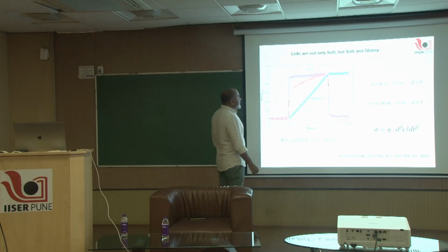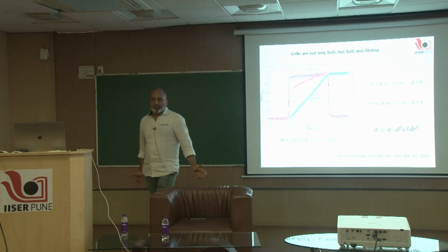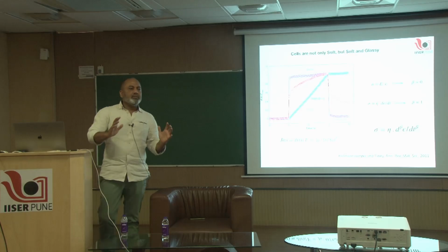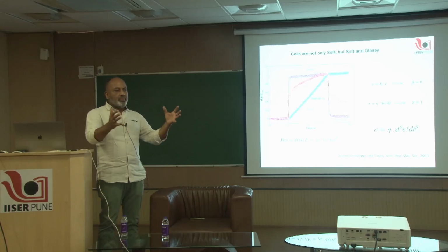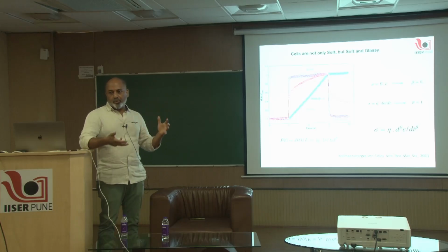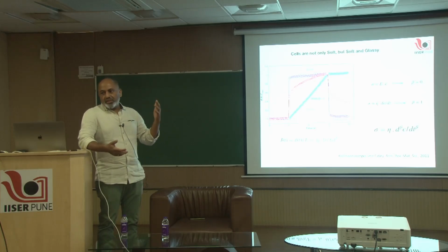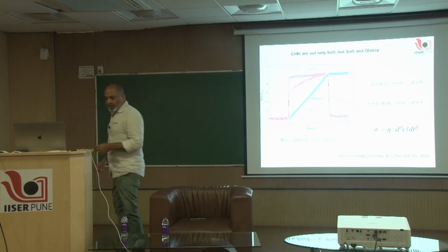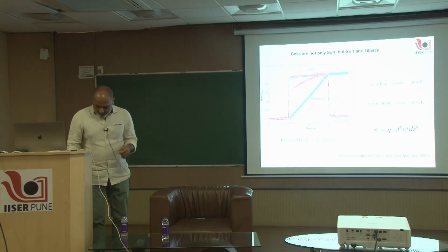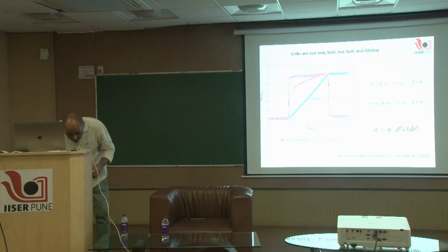And if it is a Kelvin-Voigt kind of material, I can describe the material simply as an elastic part and a viscous part, a spring and a dashpot, arranged either in parallel or in series. If it is arranged in series, one calls it a Maxwellian or a Maxwell fluid. If you put them in parallel, then they are called a Kelvin-Voigt material.